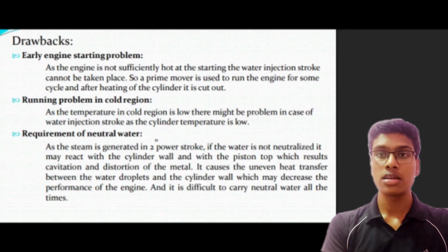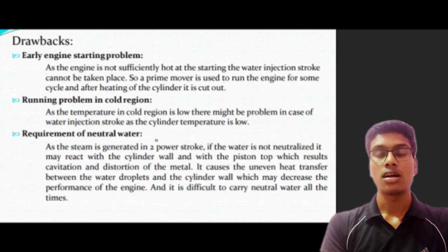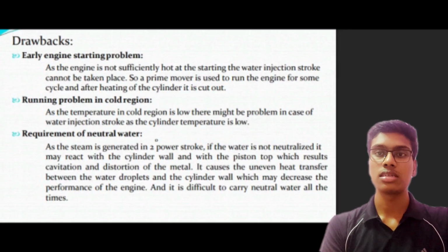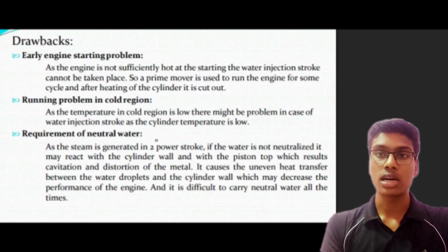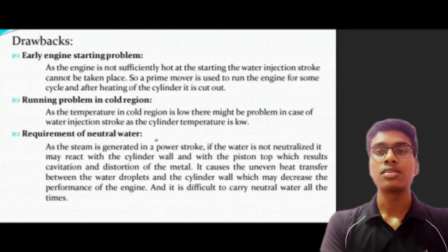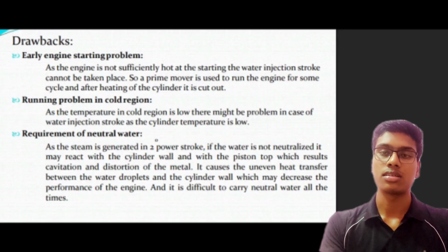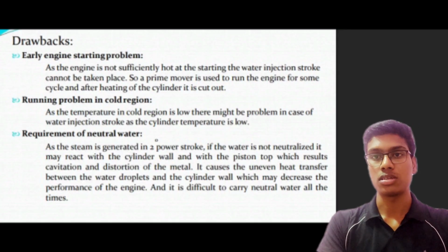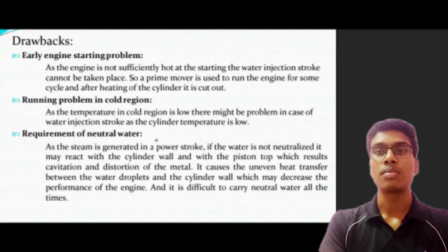For the six-stroke engine, till now there are no standards, and this is one of the reasons. It is also not suitable in cold conditions, meaning wherever the temperature is very low, because we are adding water. For example, in hill regions when the temperature is very low, if water is added, then the bike or any kind of vehicle, cars, will not start due to this process. It reduces the temperature inside the combustion chamber, which leads to difficult starting or non-starting of the engine.